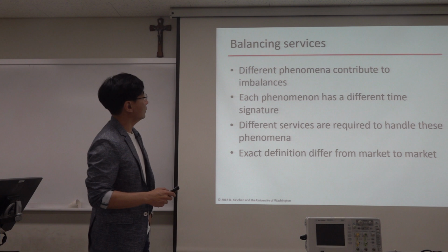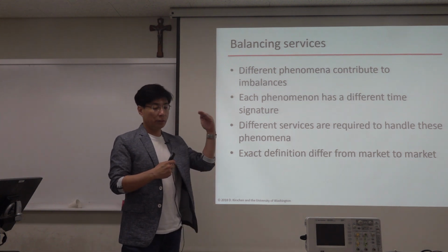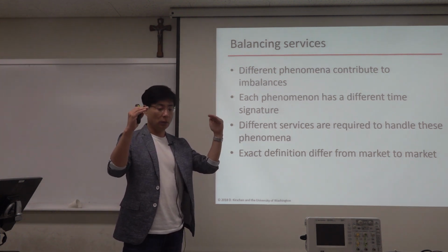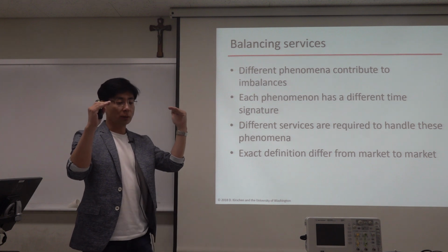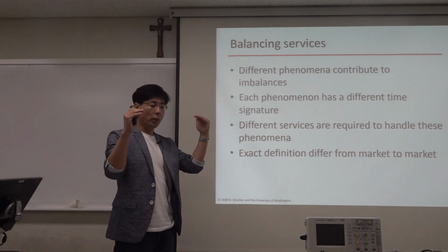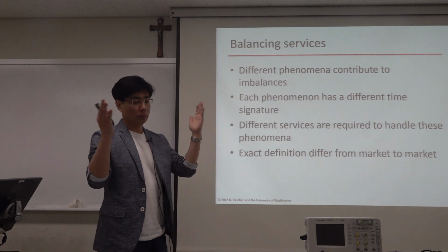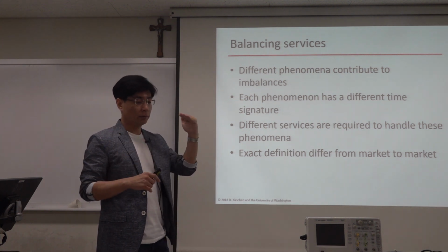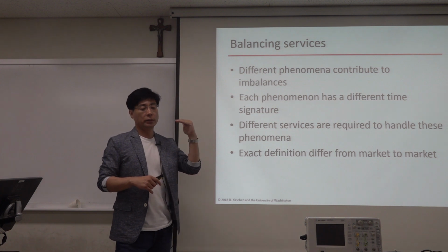So the balancing service means that the generation and the load must be equal all the time. Of course, we allow small deviation. That is about 0.2 hertz in Korea. The 60 hertz is the nominal frequency, and 0.2 hertz deviation is okay.